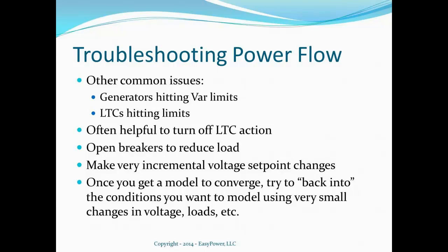Once you get it to converge and get a solution, you can start making very small changes in voltage and load to try to back into the system that you're trying to model.